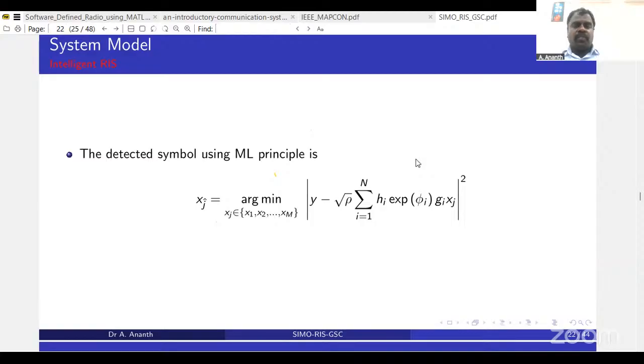So, for an example, you have a BPSK symbol which is being transmitted. The signal points of the BPSK symbol are either -1 and +1, which may correspond to the bits 0 and 1. Now, if there is no noise introduced by the system, at the receiver side your received signal also will be on the same signal point, either at -1 or at +1. Whereas in the presence of noise, your received signal will not be on the same signal point; it may be scattered somewhere nearby.